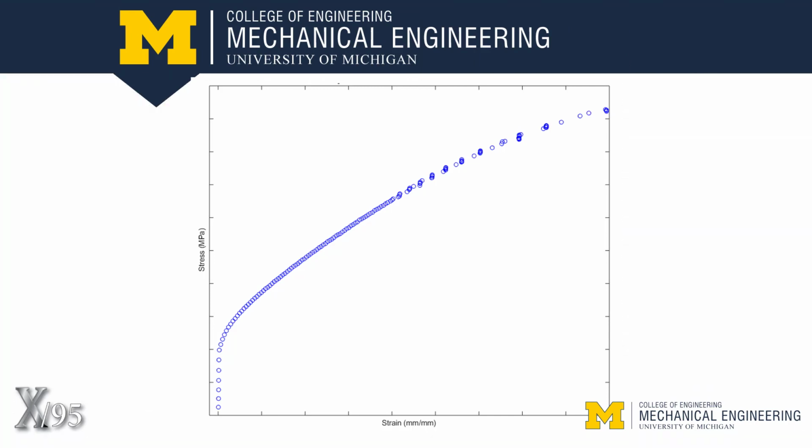A typical plot from the previous analysis is shown. Unfortunately, skipping every 10th frame does not provide enough data points to calculate the elastic modulus. We'll perform a second study using an increment of 1 and focus only on the elastic region.